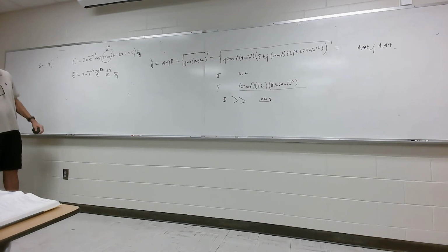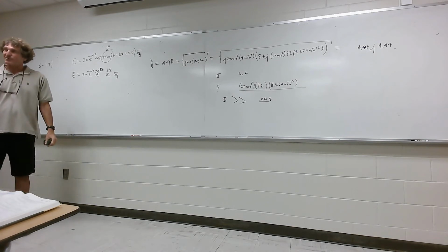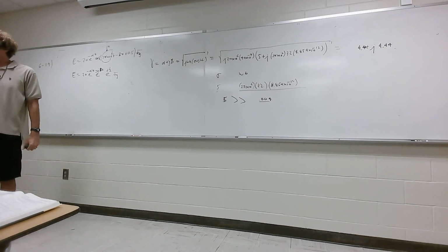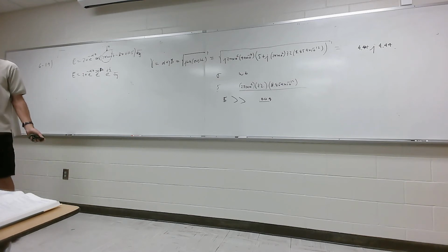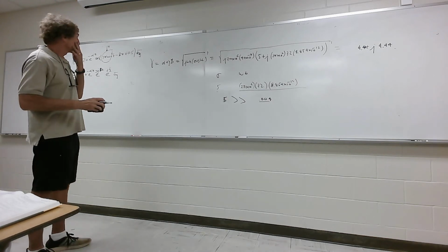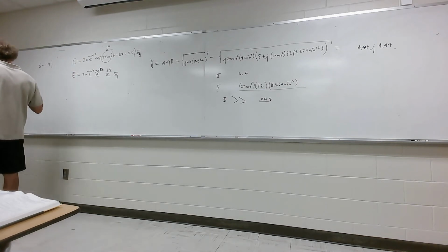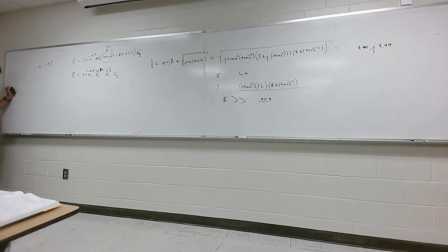Now, we want to take this and we want the value of H, correct? To get that, I'm not going to take the curl of this and divide by minus j omega mu. What am I going to do? I'm going to calculate eta, right? So, looking at this, it's a good conductor. Do y'all agree with that, class? We proved that. So, if it's a good conductor, eta technically is what? Square root of j omega mu over sigma plus j omega epsilon, right? That's the technical definition. But being a good conductor, what can we do? Yeah, get rid of that stuff, right?